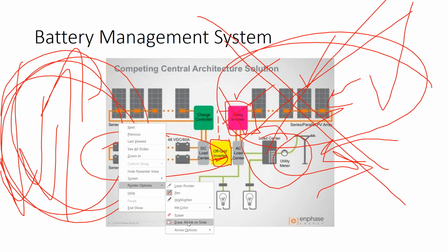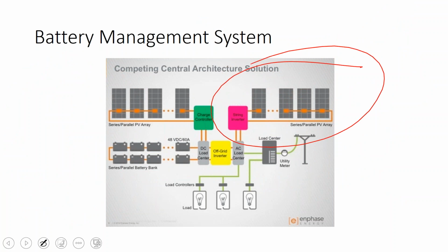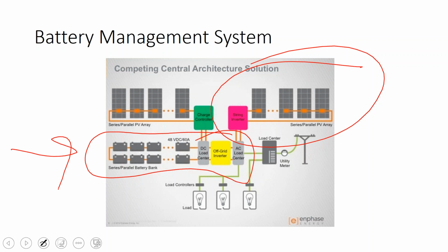But if I'm just doing a battery retrofit and I see that there's a Fronius solar array on site and there's no Fronius battery inverter, we have to remember that for residential grid-connected retrofits, the battery is really just kind of sitting there hanging out, not doing anything anyway. So this system elegance is not necessary. It's only necessary in off-grid. So I wouldn't worry too much about there being a mismatch between battery inverters and solar inverters.